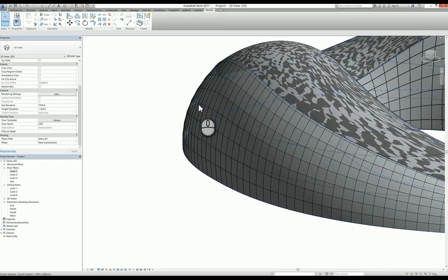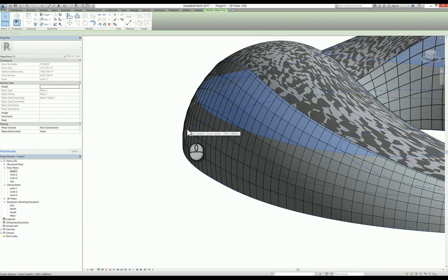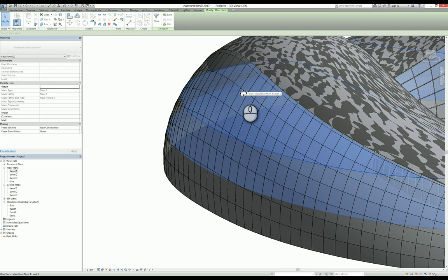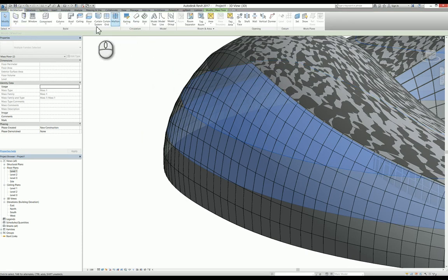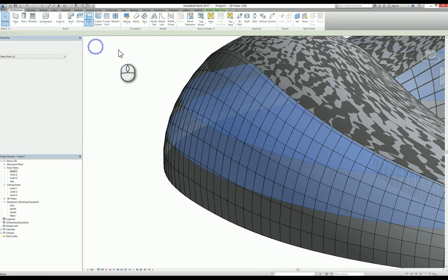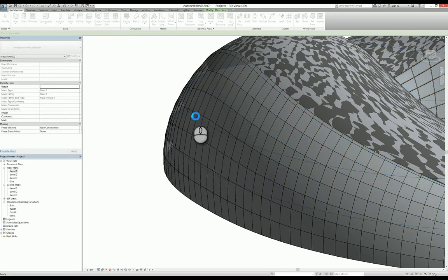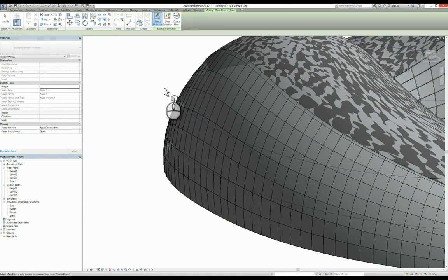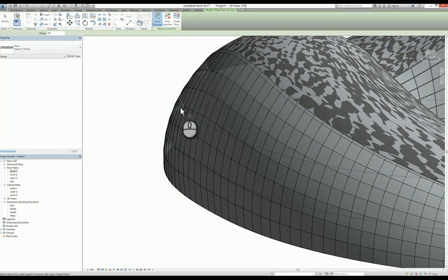Okay, the floor inside. If you see the control, this is 2 floors now. Okay, so that's one. You will create this one as a floor by face. Create Floor by Face. Create a floor. Click, create a floor. So that's now a floor.